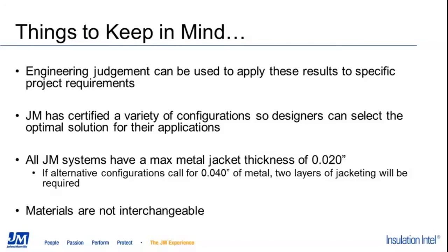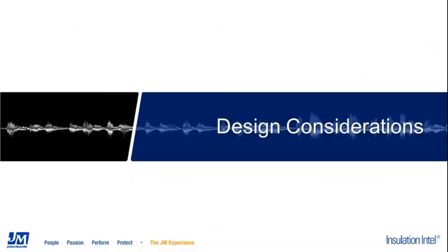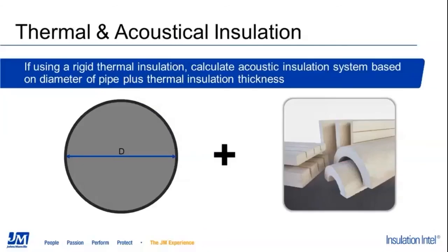That configuration, that specific material, does have to be independently tested and certified to make sure that it meets the ISO requirements. Real quick, I'll touch on some design considerations, as I mentioned, for thermal and acoustic systems, and just hit on 2 highlights here. If you are using a rigid insulation for your inner thermal layers, like a calcium silicate